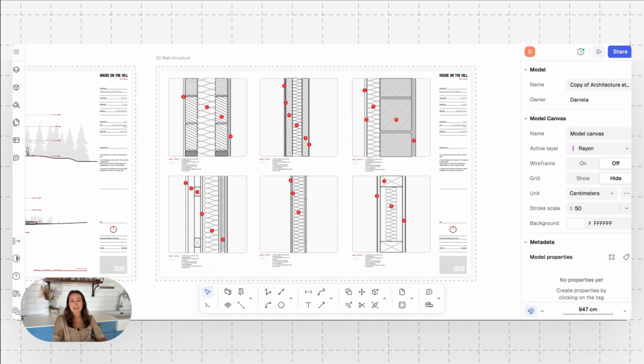Typically, a very detailed section is included to show the client that we're thinking about what's important to them and to this design. So as we discovered, this house on the hill is going to get quite a gust of wind. There's going to be strong winds in this area. So this wall insulation that was specified is actually going to be the solution to that. So this is actually how we're going to address that issue. So this is a very, very smart thing to include in your drawing set, if that's the case with your project as well.